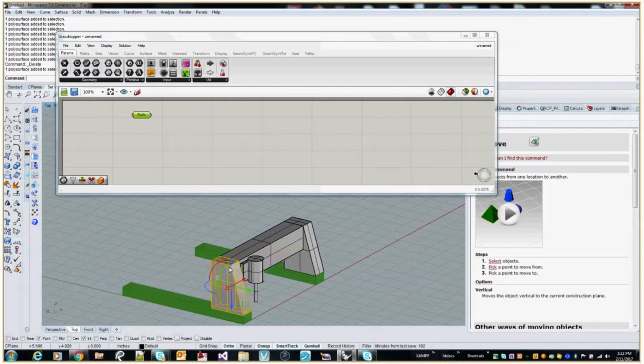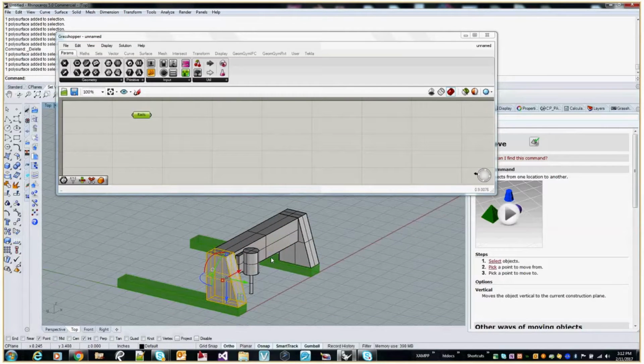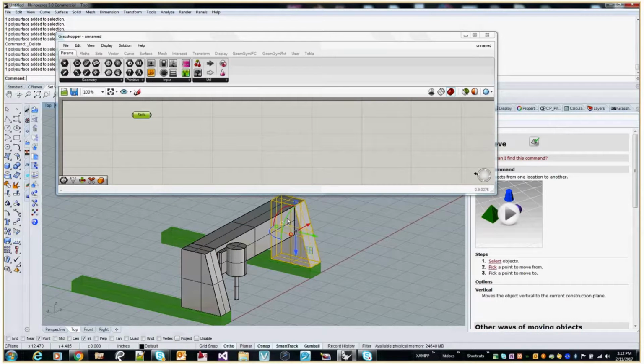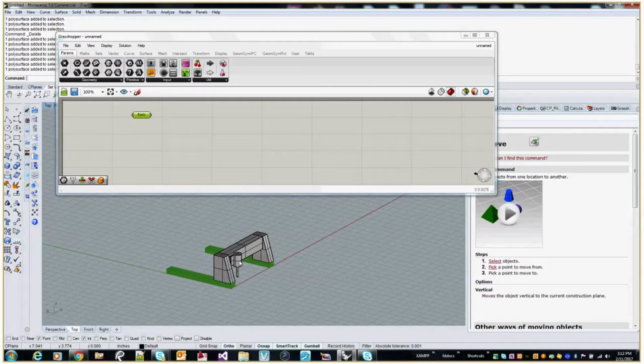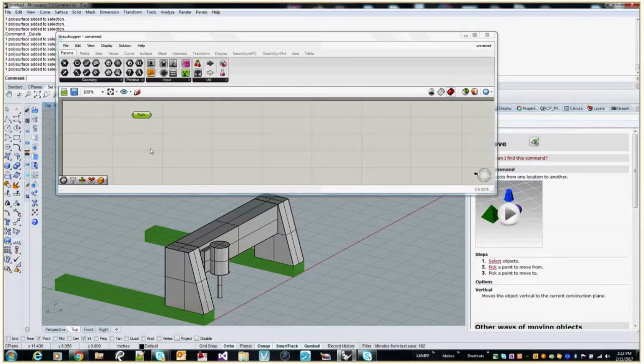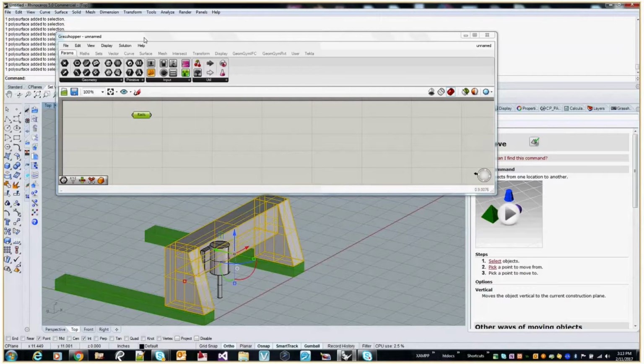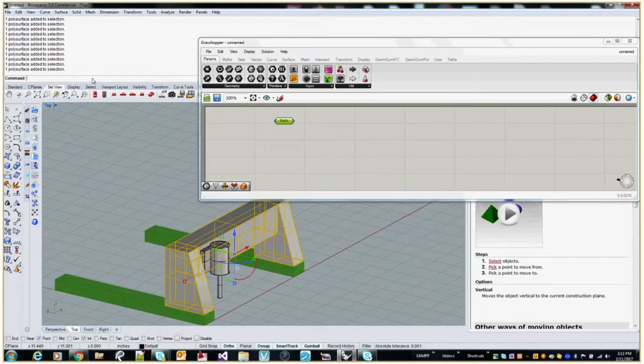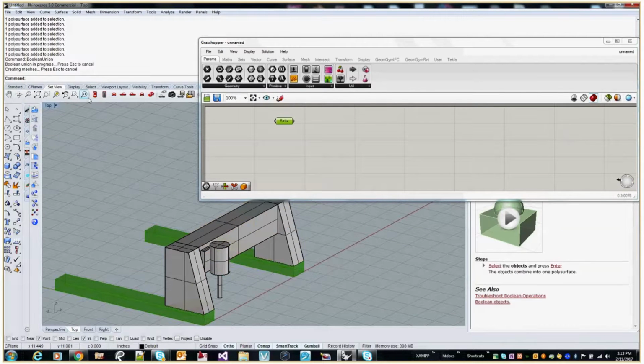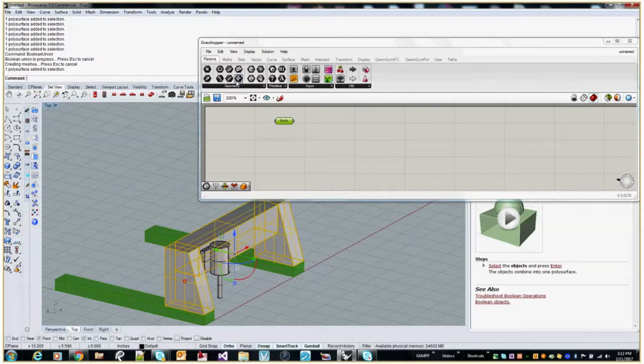The next one is our gantry bridge. What I'd really like to do is just union these together. They're not going to move apart from each other. It's going to make the actual definition a lot easier to deal with in Rhino. I just don't want to deal with 3 separate parts. It's just unnecessary work in here. So I'm going to go ahead and just grab all of these. And in Rhino, not Grasshopper, I can just say Boolean union, hit enter, and that created one object out of that, which is great. So instead of having to deal with 3, I deal with 1.